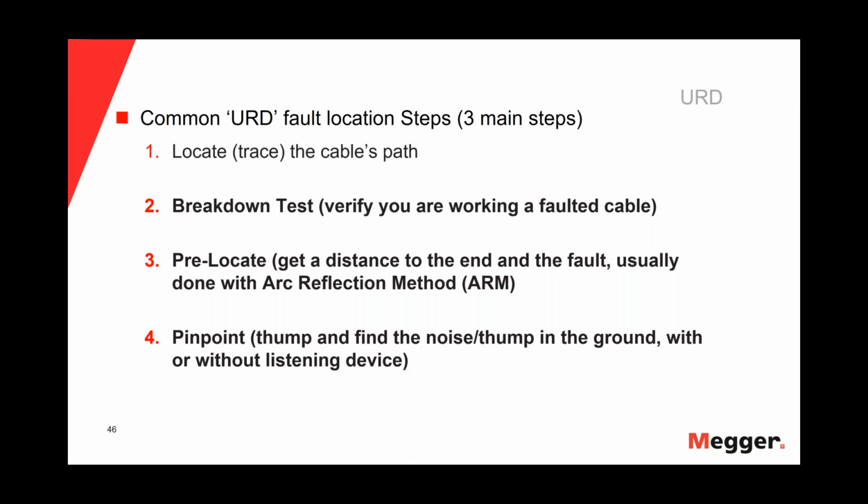Once we've verified that we're working a faulted cable, oh, there's one other thing: if you can't verify that you're working a faulted cable, the last thing you want to do is start thumping on a good cable. That would be similar to the problems that you would have on thumping on cable too long for the thumper. All that voltage then comes back into your thumper. You could damage a thumper by thumping into a good cable. So the breakdown test helps you avoid that particular issue also.